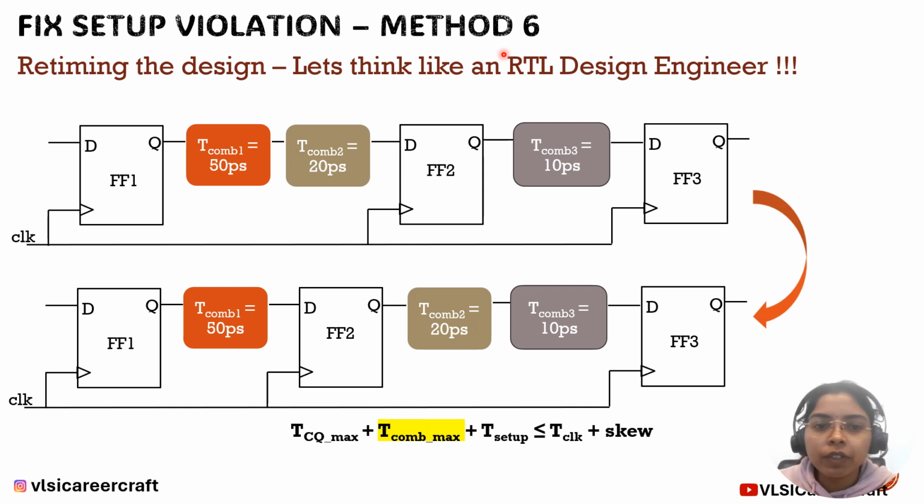One more method of fixing setup violation is retiming the design. What is meant by retiming? Let's say I have this pipeline design and I have two stages. This is one stage and this is the second stage. So what are the combinational delays here? I have 50 plus 20, that is 70 picoseconds of combinational delay here, and 10 picoseconds there. We consider the worst case for setup violation. So I see 70 picoseconds is very high to satisfy this equation, so I'm having a setup violation here.